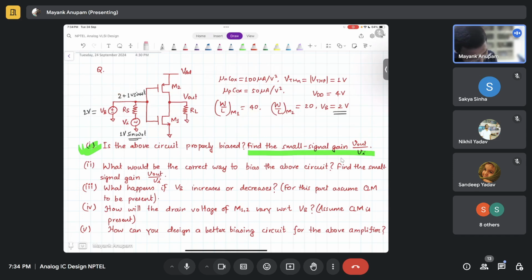Why is that? It doesn't matter if there is Vi placed here. You see this voltage VB here, right? This voltage VB is directly connected at this terminal, right? It is shorted with this terminal. And we know that a voltage source knows nothing. It's a king, right? In its own world, and the moment it is placed somewhere, it will try to impose its own rule. If it is shorted to some network, it will simply impose its own condition that the voltage there should be exactly 2 volts, no change, isn't it? So the voltage here will always be 2 volts.